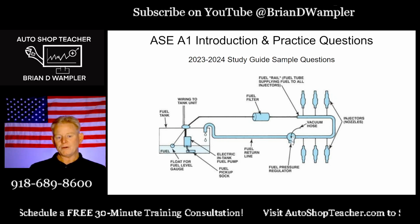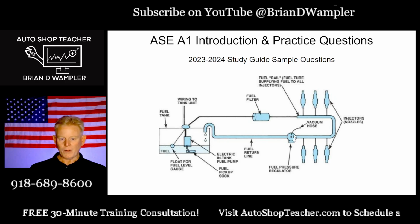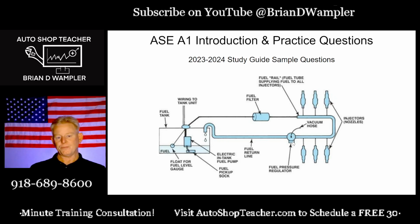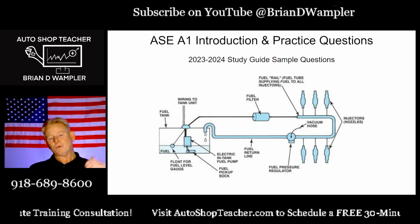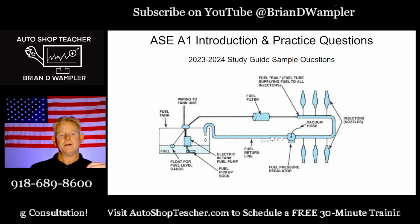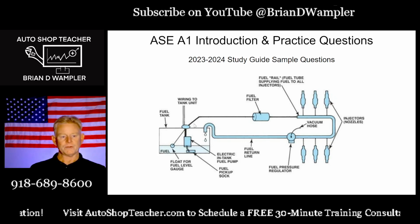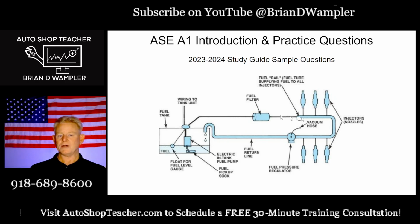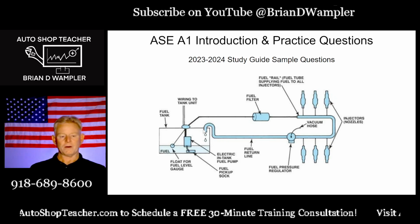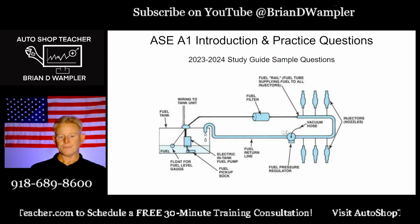So by putting a restriction here that we call a fuel pressure regulator, think of it kind of like the dam that's going to hold the water, or in this case the fuel pressure, up to a certain point. Once that amount of pressure is reached, the excess pressure that's unneeded returns back and drops into the tank. That's why we call this a recirculating type fuel supply system, because the excess fuel is returning. So either a recirculating or a return type fuel supply system.